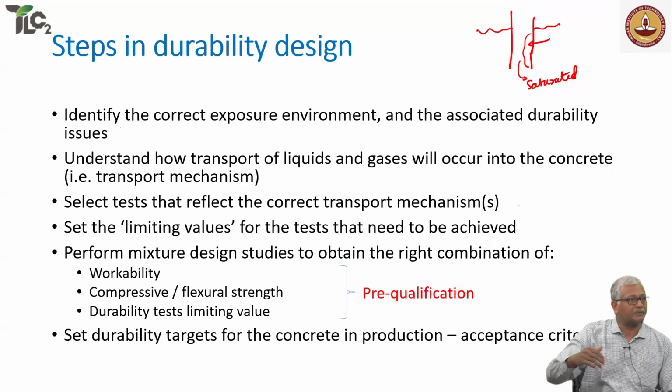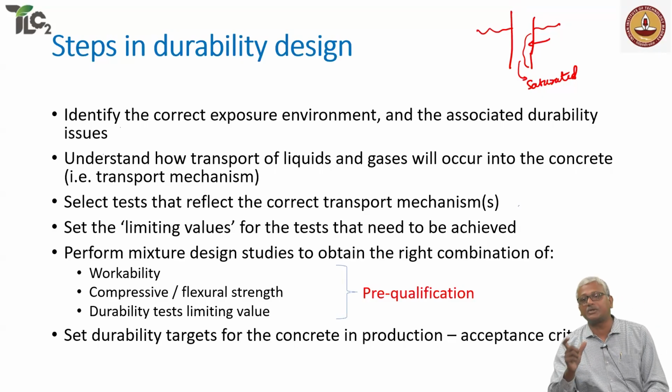As you go deeper and deeper, the pressure of water increases. So permeation can happen. And the chlorides in the seawater are higher than in the concrete, right? So diffusion of chlorides can happen. So all these happen in a saturated condition.